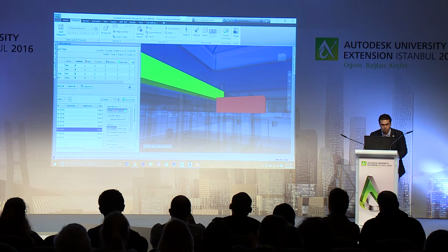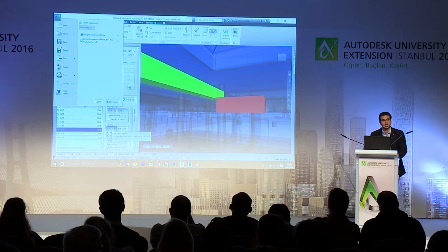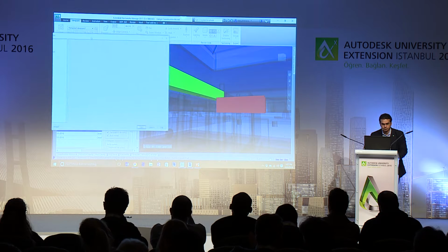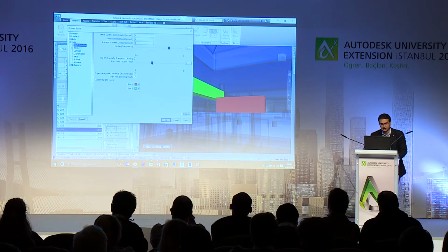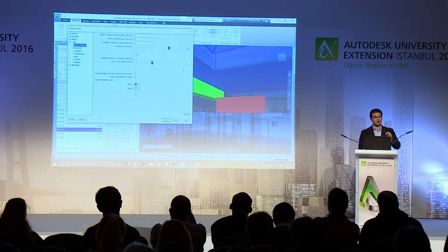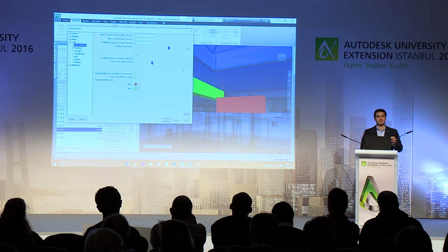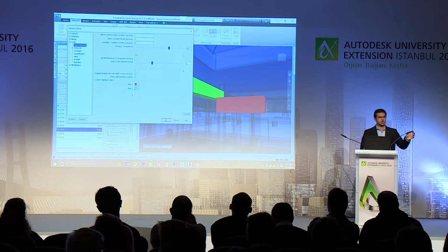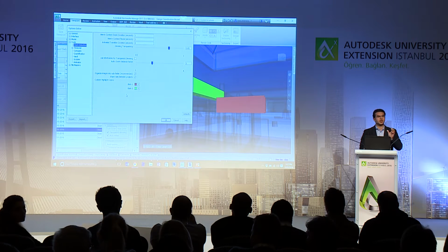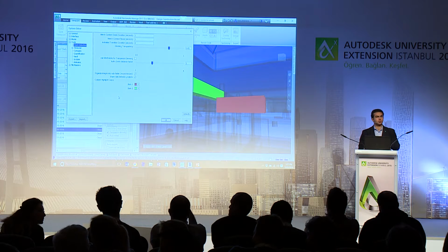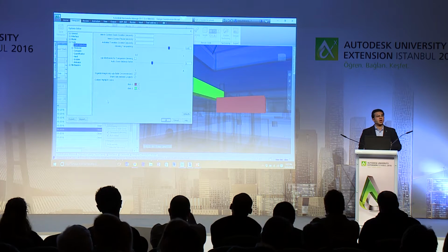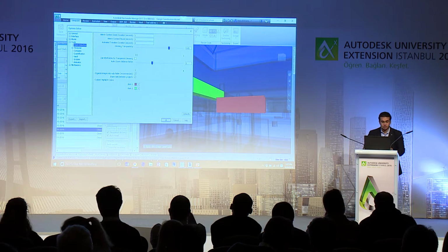One thing also that you might know, when you do the dim others here, if you go to Navisworks options, under tools, you go to the clash detective, you can control the type or the colors that you want to use to represent the first one and second one. A practical application here, for example, any items related to the architectural model, I want to represent it always in red, and any item in a clash test related to the structural model, I want it in blue, and the MEP model in green. So it's kind of driving a standardization in your project. You can do this in Navisworks.